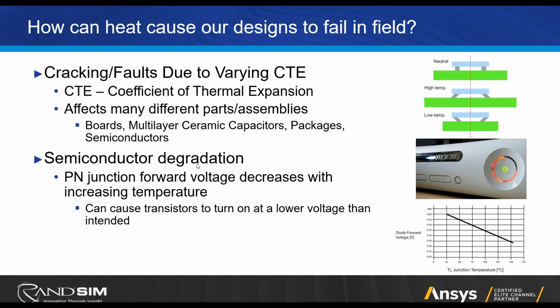But you can imagine having, if you had taken your design from room temperature to say 150 degrees, one can imagine a scenario in which a transistor which didn't used to be on is now on, and when you are not intending, potentially causing some big issues for design.